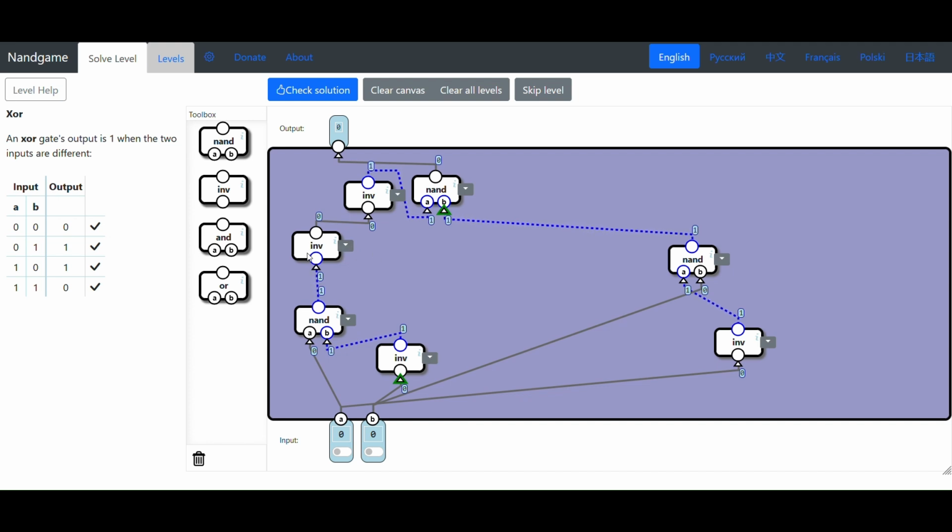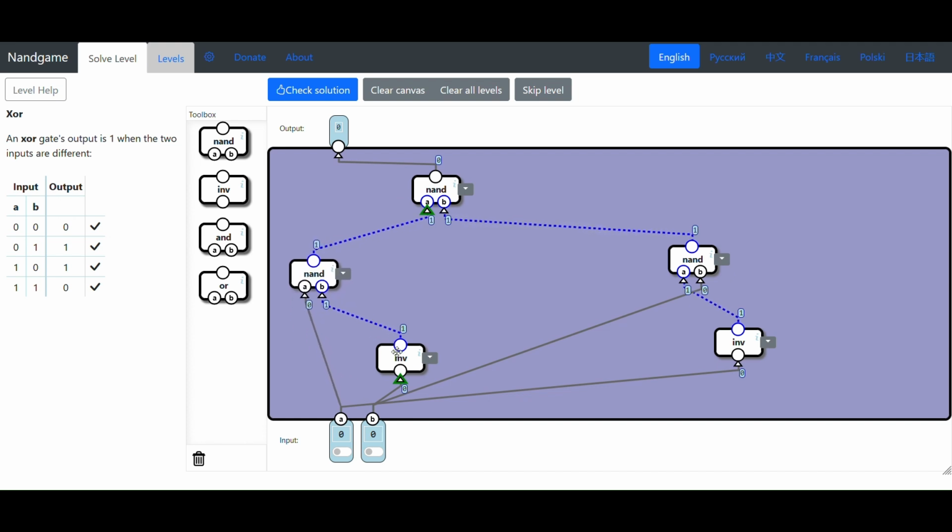But let's just assume it takes 10 nanoseconds to go through this NAND gate, this inverter, and this inverter before it finally gets there. That's a huge delay as it stacks up, with two of these being like a 20 nanosecond delay here. So we can just get rid of that altogether and bypass it, and it still works.